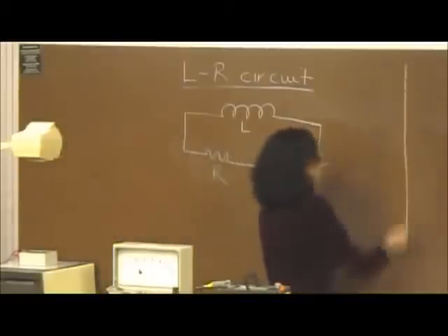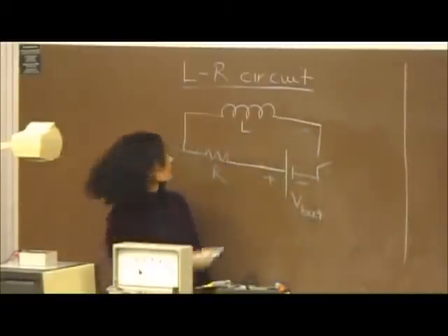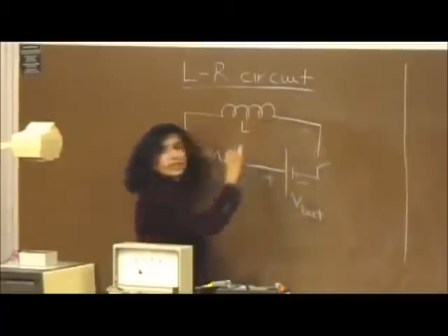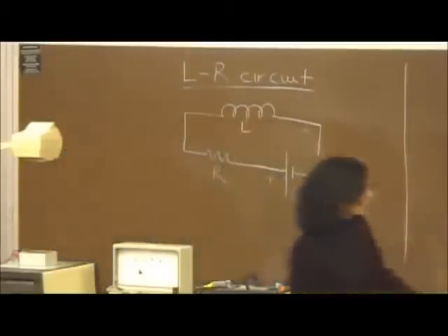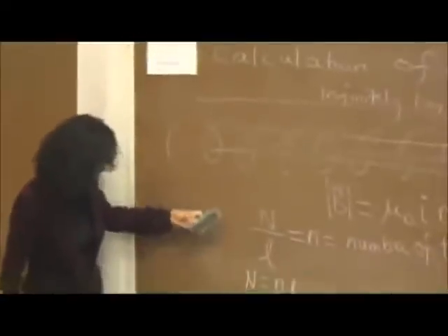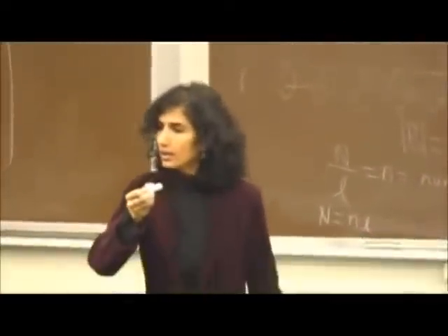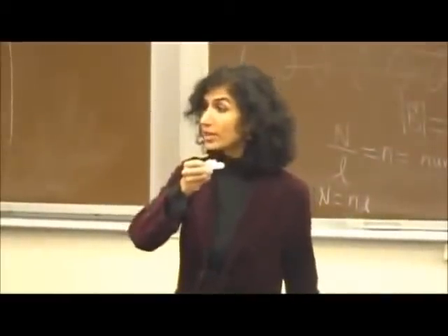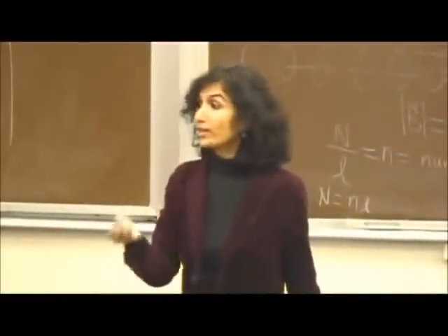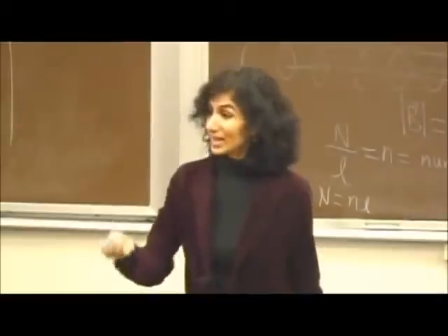Now here is the thing. From Faraday's law, as soon as we close the switch here, what do you think will happen in the inductor? I already talked to you about it. I just erased it. Remember I said to you the current will not immediately become maximum. It will gradually go to its maximum value. Why? Because the coil will see a change in its magnetic flux.